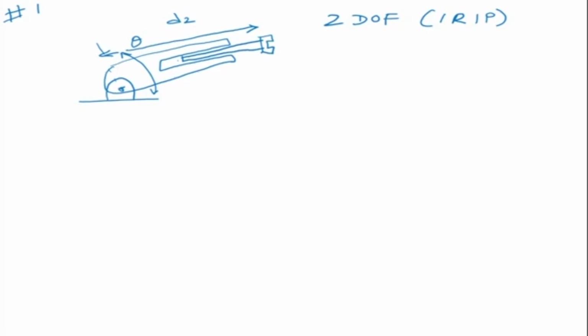First, let us assign our axes. How do we assign our axes? Let me use red color. The Z axis is the axis of rotation, so this is my Z0 and Z1. Then which is my X axis? Now you have to be a little bit careful here, in the sense that when you have a prismatic joint, you have to be careful about the X axis, because we want to find the distance between the axes. So Z0, Z1 is here.